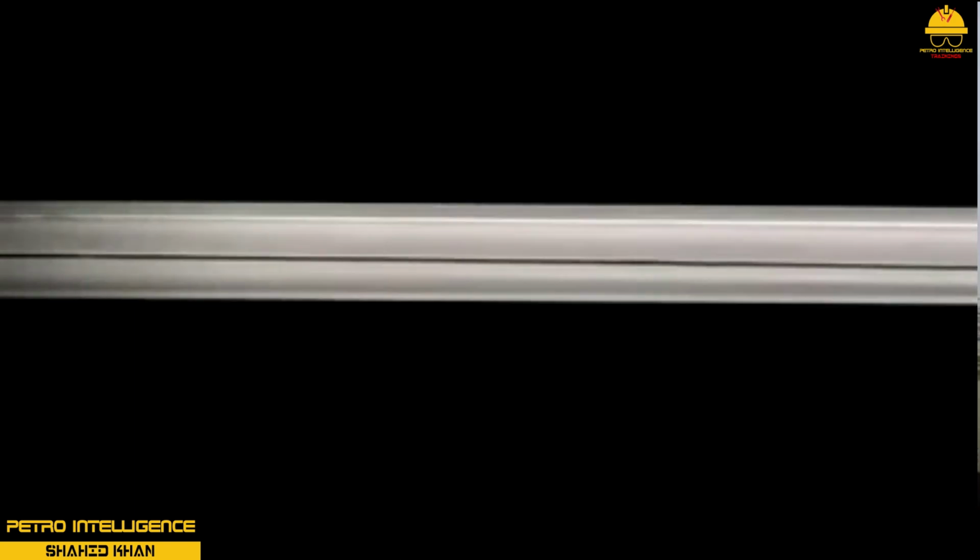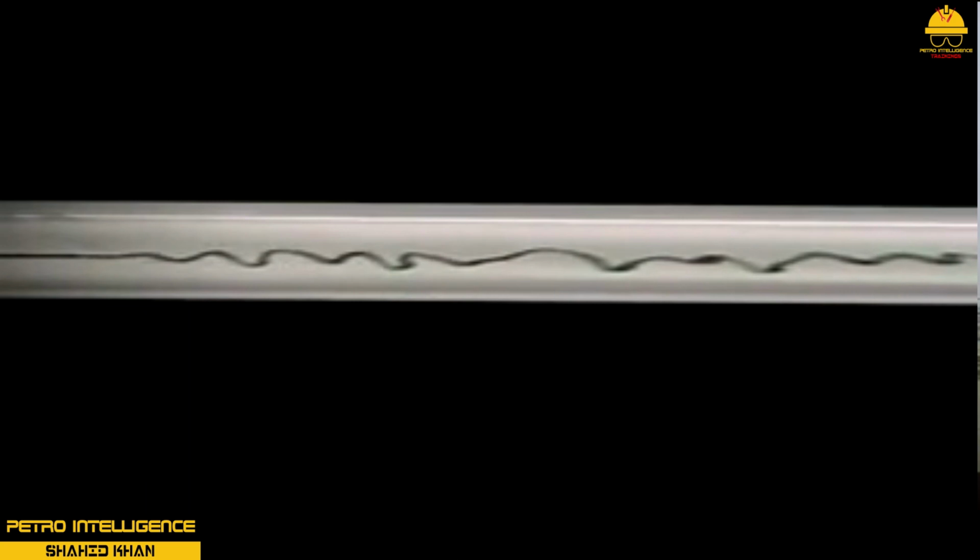Turbulent flow is the random movement or mixing of fluids. Once the turbulent flow is initiated, molecular activity speeds up until the fluid is uniformly turbulent. Turbulent flow allows molecules of fluid to mix and absorb heat more readily than does laminar flow. Laminar flow promotes the development of static film, which acts as an insulator. Turbulent flow decreases the thickness of static film, increasing the rate of heat transfer.